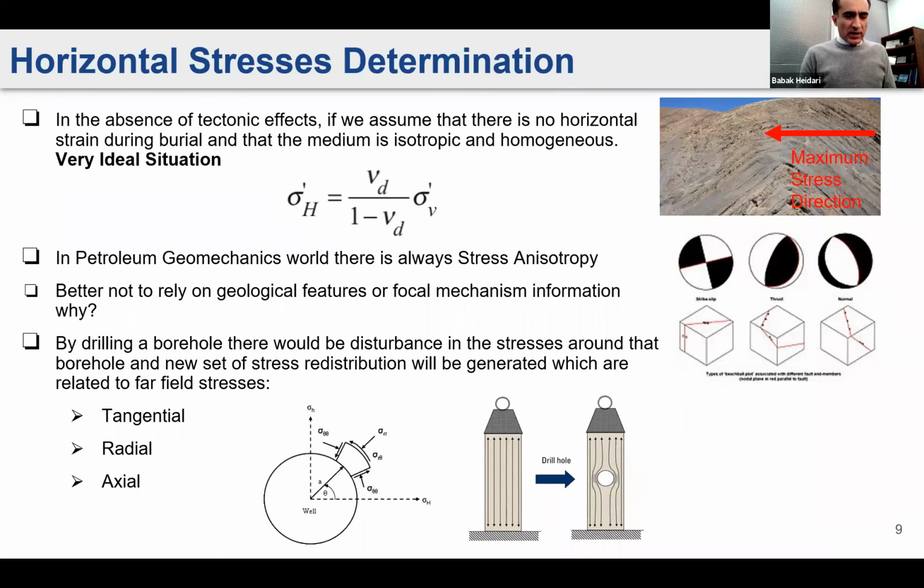You can build a geomechanical model based on gamma ray data, and you can invest heavily in the sonic scanner, the instrumented packer, intelligent packer, or more advanced measurements to come up with a more sophisticated model. It depends on your application, but there is always something. Even the world stress map I mentioned can be a starting point for you. It can provide good information.